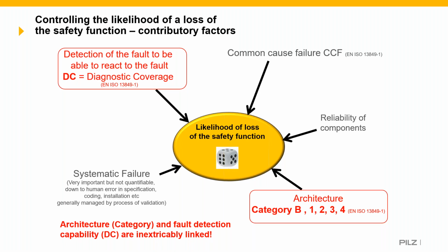The chance of a dangerous failure is not only based on the reliability of one component, but it depends on the total loop. So all the parameters which we design are effective on the total calculation, and it depends on the whole structure. Diagnostics coverage measures the effectiveness of the diagnostics, which may be determined as a ratio between the failure rate of detected dangerous failures and the failure rate of total dangerous failures. And bear in mind that diagnostics coverage can exist for the whole or parts of a safety related system. For example, diagnostics coverage could exist for sensors and/or logic systems and/or the final elements.